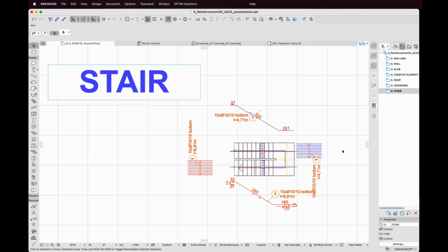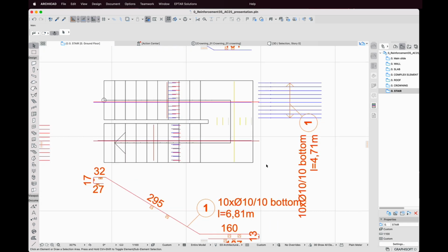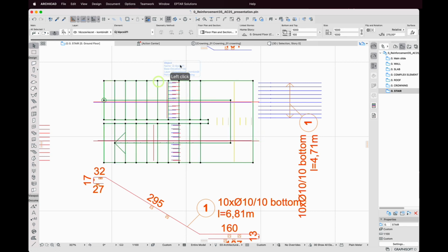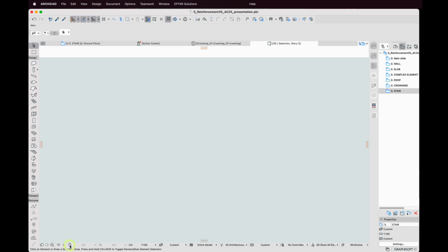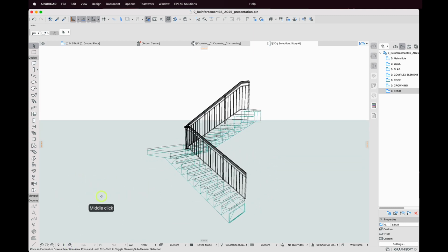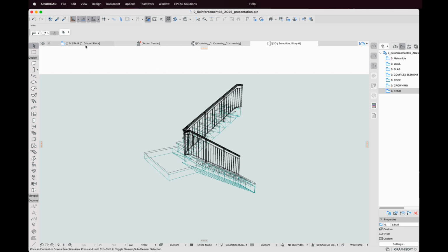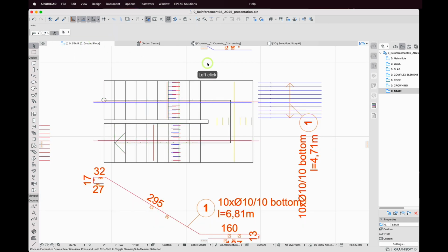Custom shape rebar. Next is the construction when the standard rebar is not enough, and we need to make a special reinforcement. The best sample for this is the stairs, because stairs have a very flexible shape. We cannot place automatically the straight, horizontal or vertical reinforcement. We have to use a polygon rebar for it. Here is a very simple stair. Let's check it in 3D. Let's see how I can place reinforcement elements into this. I will place everything manually.